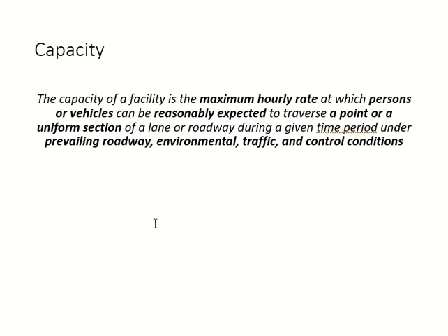So according to the manual, capacity is defined as a flow rate, okay, maximum flow rate, not volume. If you go back to chapter number 1, you will find that maximum flow rate is much safer to design for, or much safer to be taken as capacity, because when you take the maximum flow rate, then you are sure that the capacity of the highway will not fail even in the 15 minutes within the peak hour. If you just take the volume, then there is a high chance that you may exceed the capacity in any 10-15 minute period, and it will ruin the entire hour or maybe more than 1 hour. Okay, so capacity is taken as maximum flow rate.